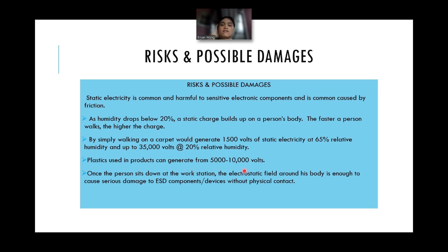Plastics used in products can generate from 5,000 to 10,000 volts. So plastic also generates lots of static electricity lah. Once the person sits down at the workstation, the electrostatic field around his body is enough to cause serious damage to ESD components or devices without physical contact. So by you sitting down at your workstation, you're able to damage ESD sensitive devices without even knowing lah.